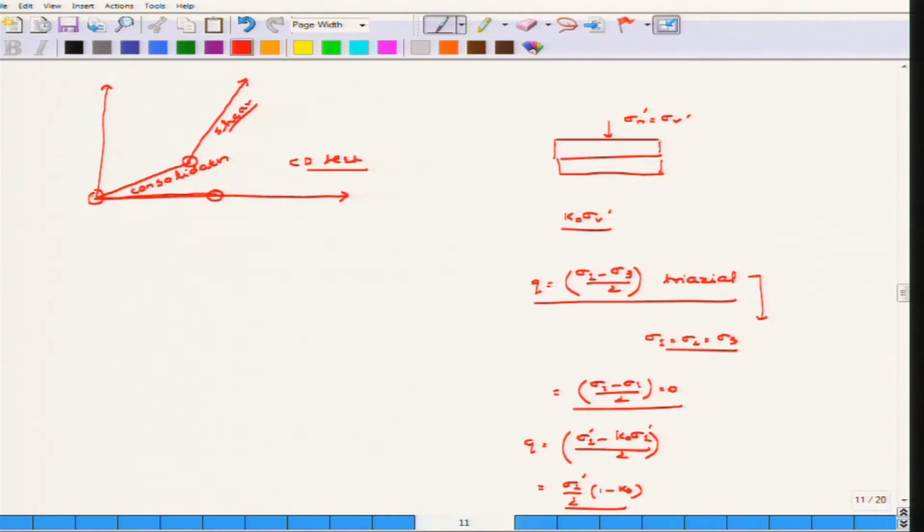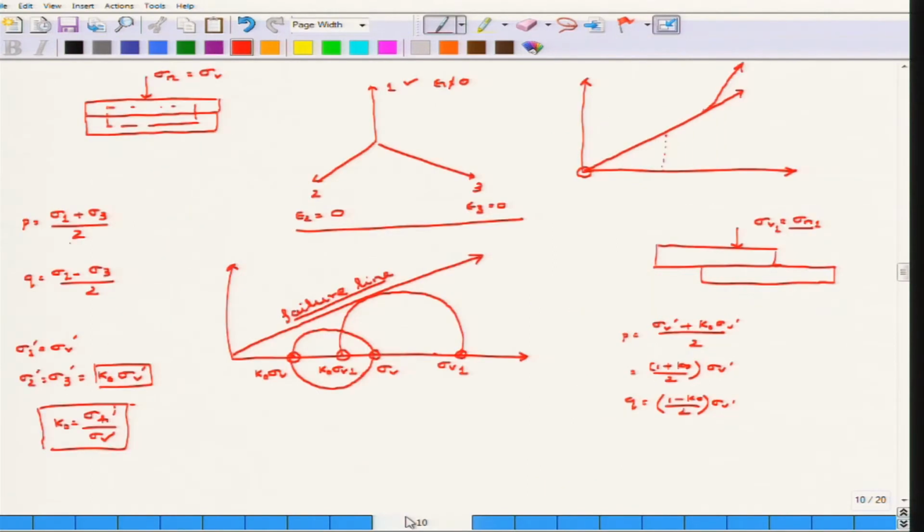Now, in case of a direct shear, as you have seen, you get a plot of shear stress versus strain. It somewhat looks like this for a particular normal stress. This is already known to you, so I am not discussing all these facts. And one important point regarding the direct shear test is that, remember, the sample is confined from all the directions, this I am again telling you. So, k naught, or the effect of k naught, should always come into consideration in case of a direct shear test.